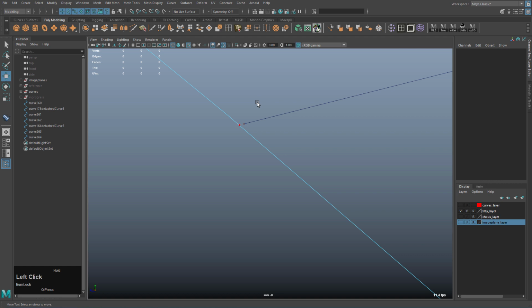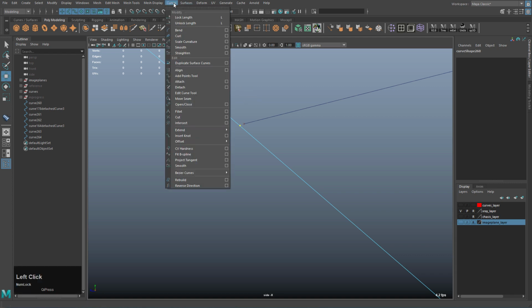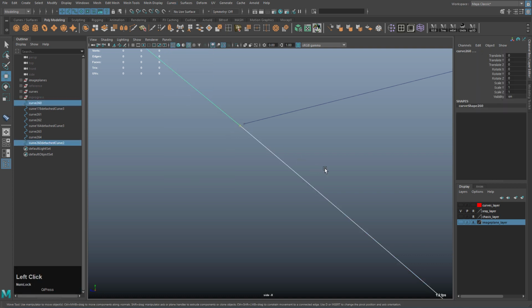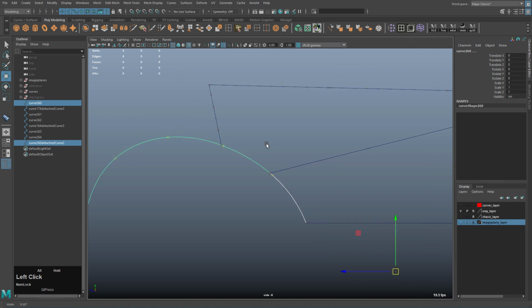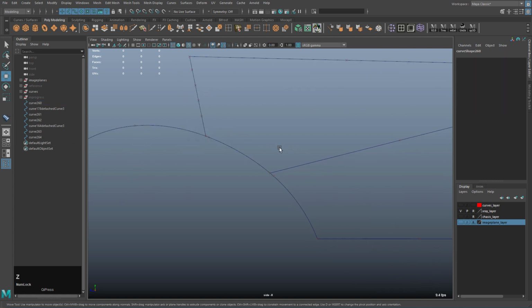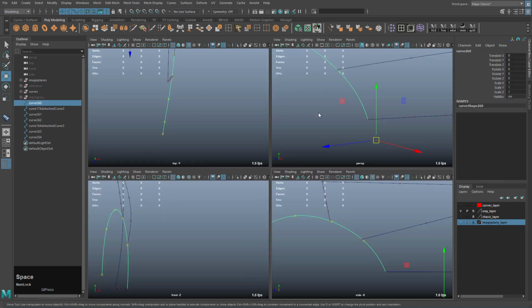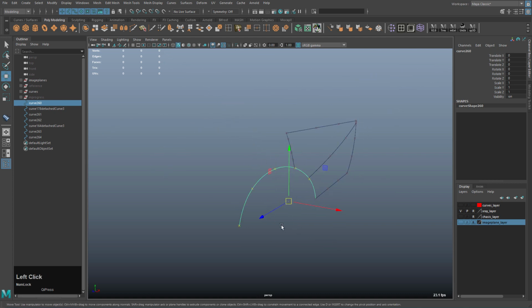So I'm going to drop it in the direction where this curve should penetrate, which is here, like that. Then you can go to the curves menu and hit detach. That's going to split them in two. Now the issue here is when you do this, your previous work on the loft will not work unless you've already done it, because once this curve is split, you can't do a bi-rail to make the fender.